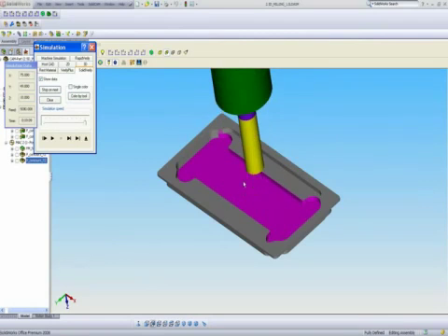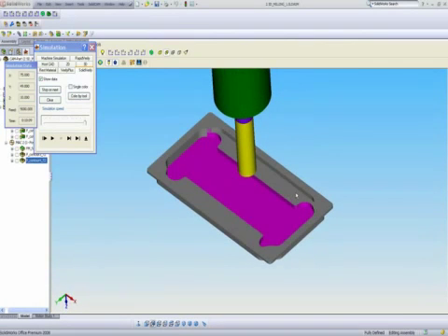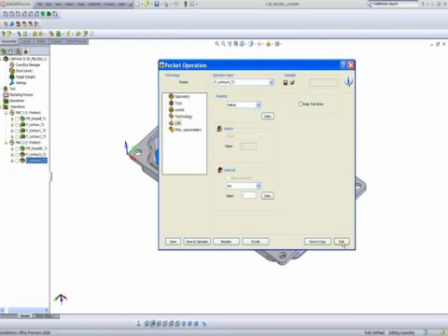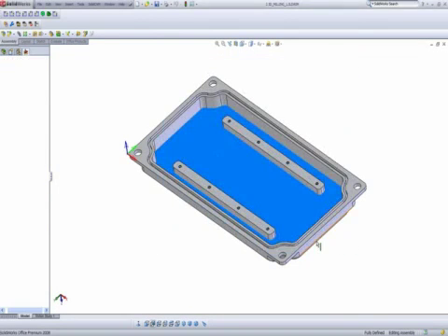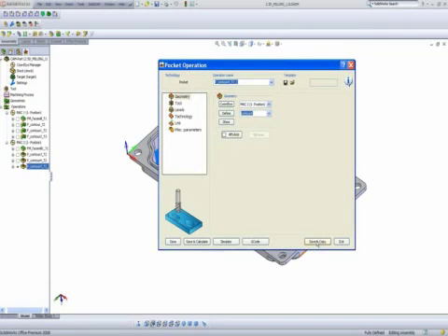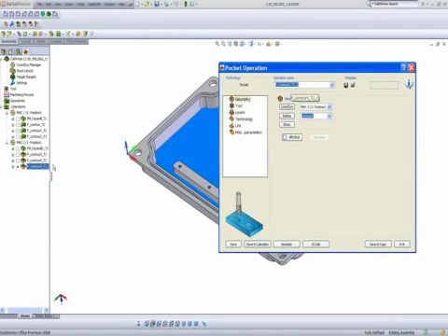However, there are areas where it could not go into, and this is very simply because the tool was too big to go into those areas. But I've decided to use a bigger tool in any case to take out as much material as possible. Therefore, for my next operation, I will do what they call save and copy, creating a new operation, as we can see here, based on the old operation. Just make some changes now in this particular operation.